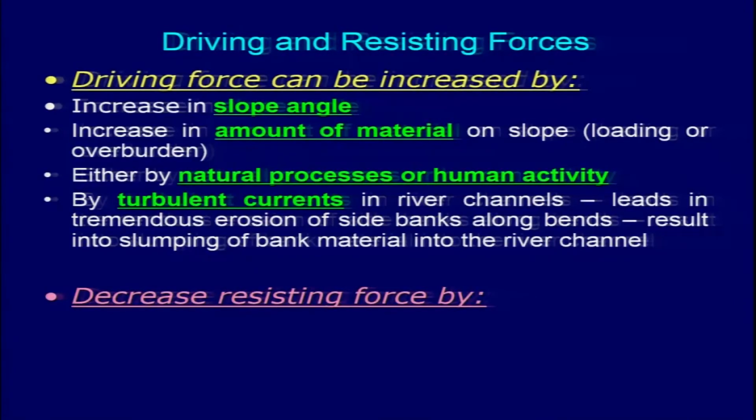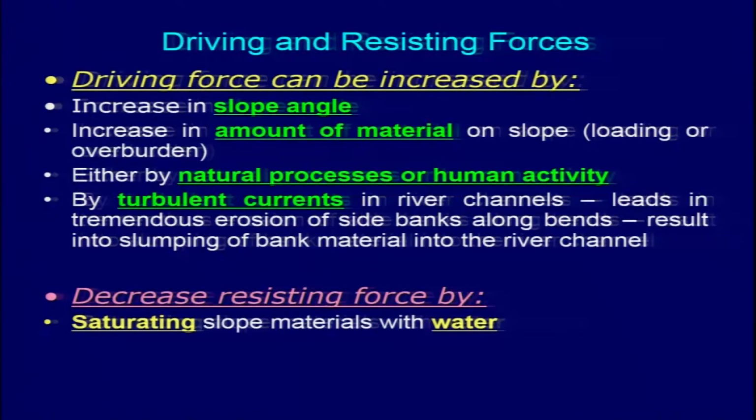Decreased resisting force can be because of saturating the slope material by water. So in most of the areas, what has been done is to allow the water to flow out, to run off as early as possible.